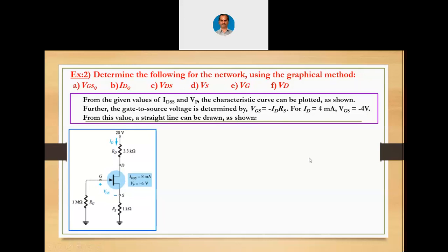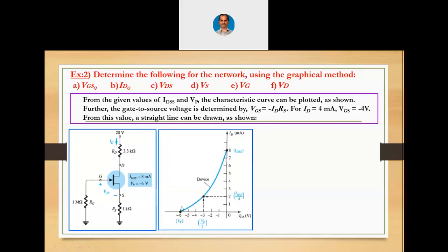So I am showing you the solution. This is the transfer curve now. Using IDSS and Vp, here he has shown only one point. Actually, only one point is not sufficient. You have to have one more point. Now, this is corresponding to IDSS by 4 and minus 3. This is IDSS by 4 and 0.5 Vp. For IDSS by 2, you will have 0.3 Vp.